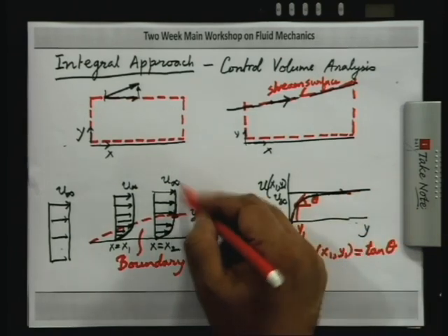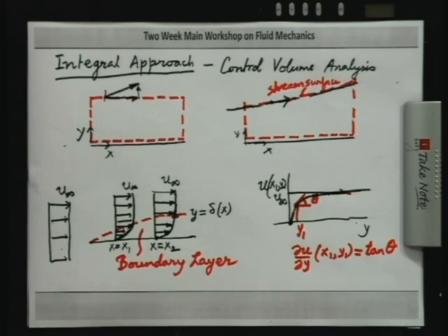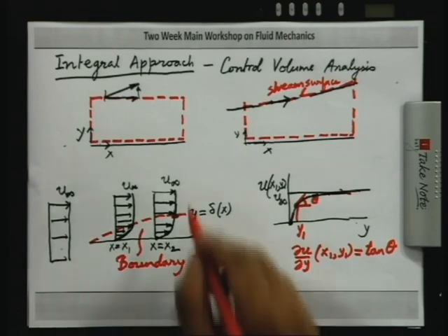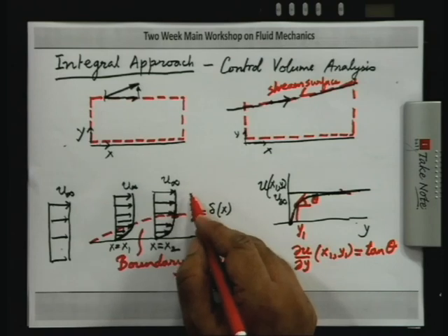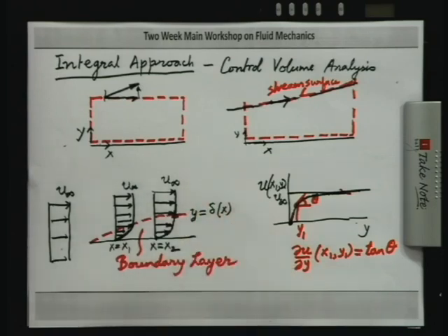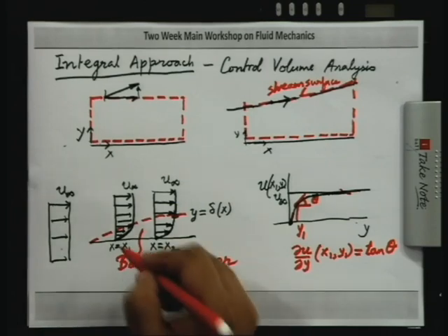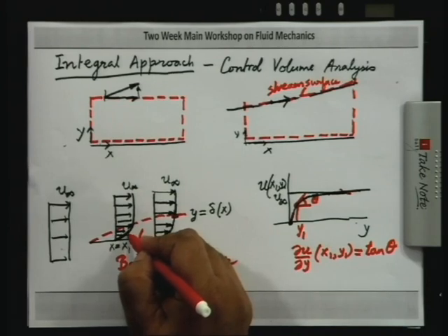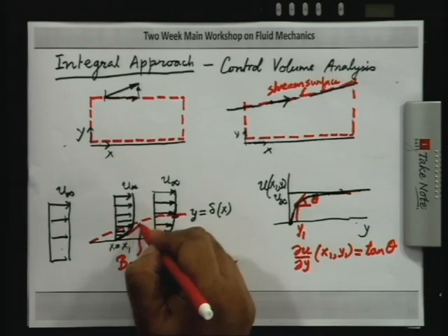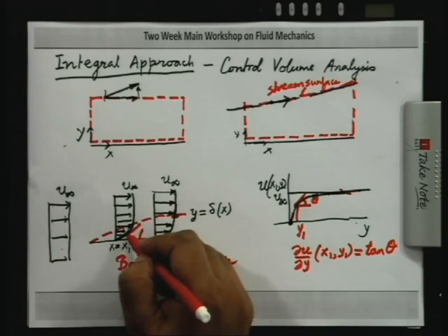So, that means that outside the boundary layer the shear stresses are going to be very small, and the fluid will behave like an inviscid fluid, although it is a viscous fluid, because the strain rates are very small, the shear stresses are going to be 0, as if it is an inviscid fluid with 0 viscosity. Now, if I consider the point y equal to y1 here and draw the tangent, then del u del y will be tan of the angle from the vertical. So, I will draw another enlarged figure to show this.